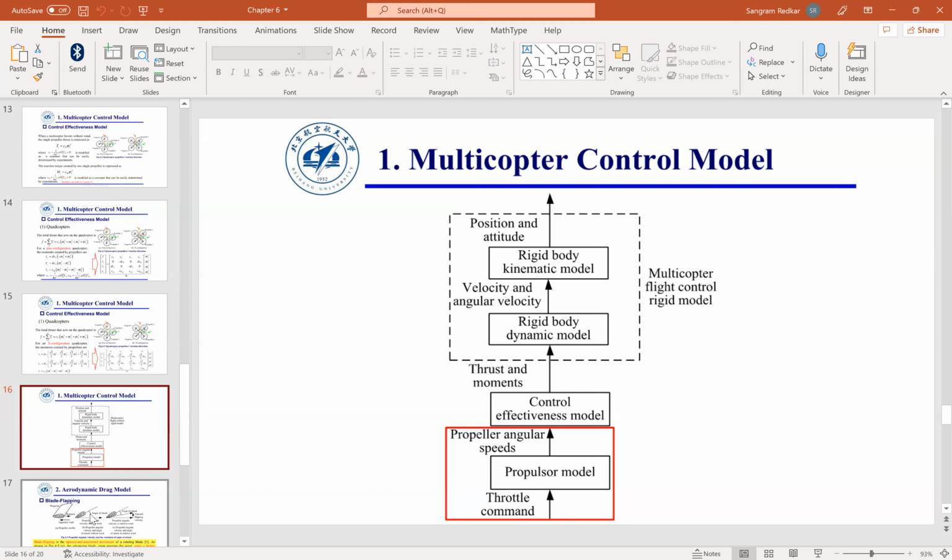I don't know if you have seen this, it may not be visible in the quadcopters, but if you look at the big helicopters flying, the helicopters don't take off like this. Because it is an under-actuated system, it basically goes like this. You will notice that the top blade on a single helicopter would be doing something like this. It will never go like this. Flapping occurs because of the differential speed between the leading and the trailing blade.